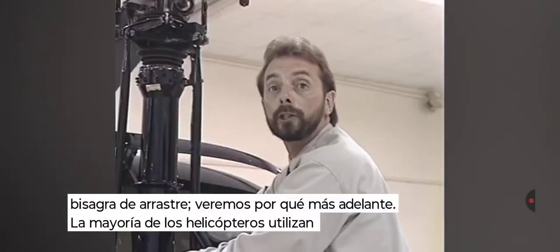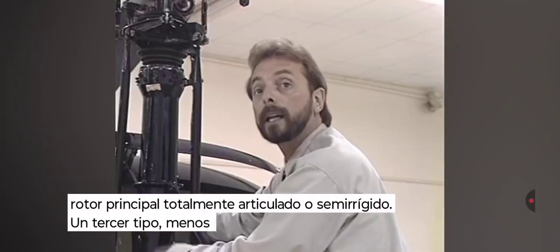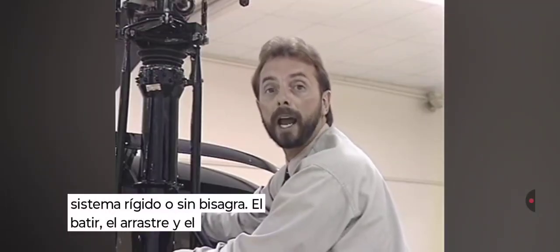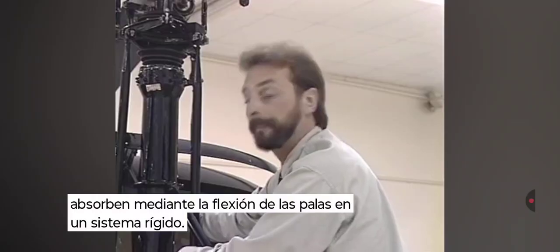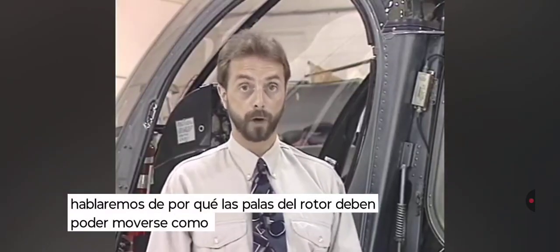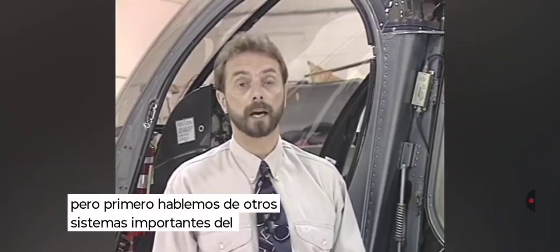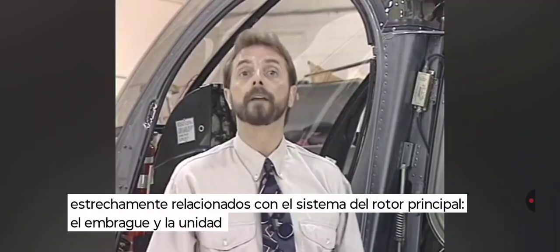Most helicopters use either a fully articulated or a semi-rigid main rotor system. A less common third type is a rigid or hingeless system. Flapping, dragging, and feathering is absorbed by blade bending and flexing in a rigid system. Later, in helicopter aerodynamics, we'll talk about why the rotor blades must be able to drag, flap, and feather. But first, let's talk about some other important helicopter systems. Closely related to the main rotor system is the clutch and the freewheeling unit.